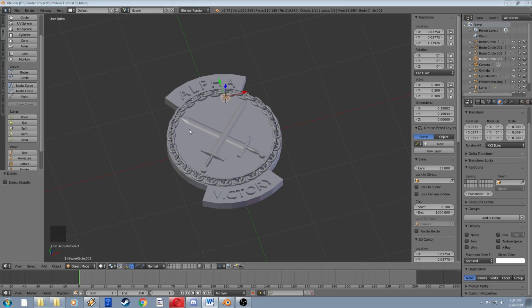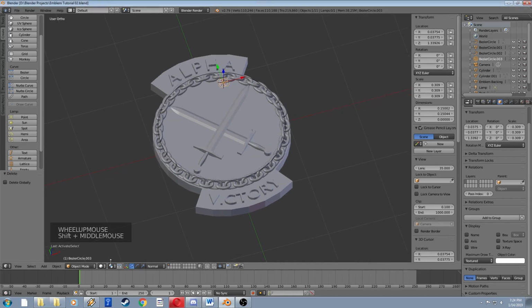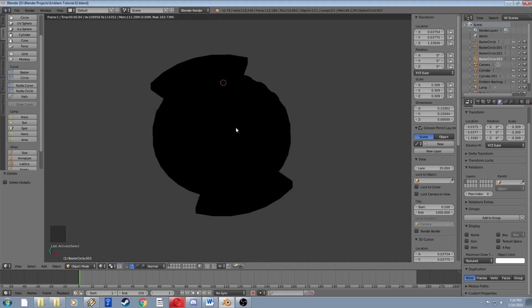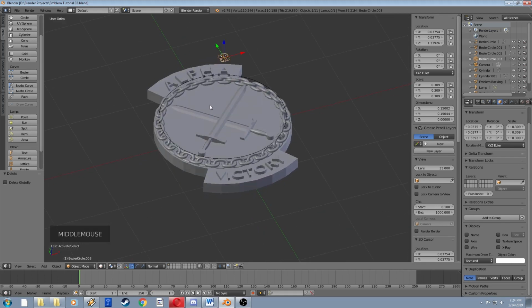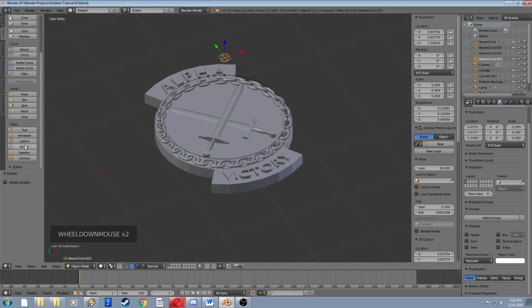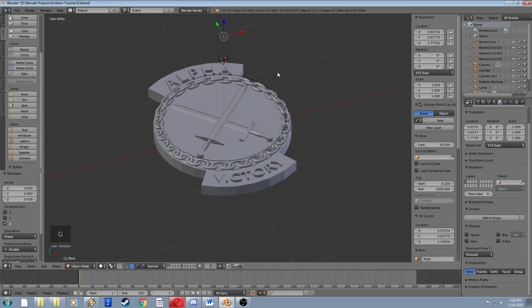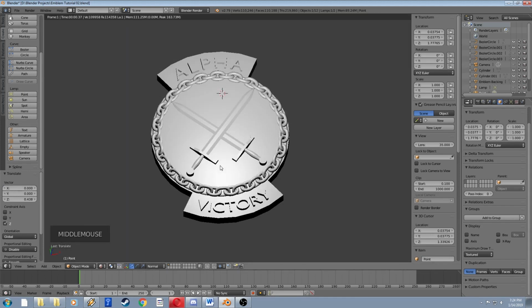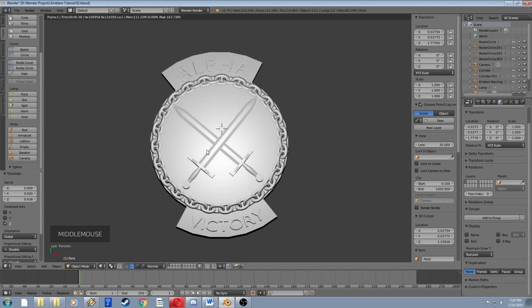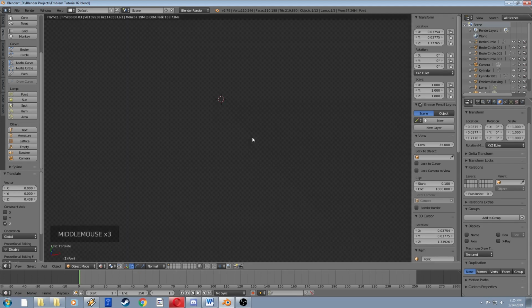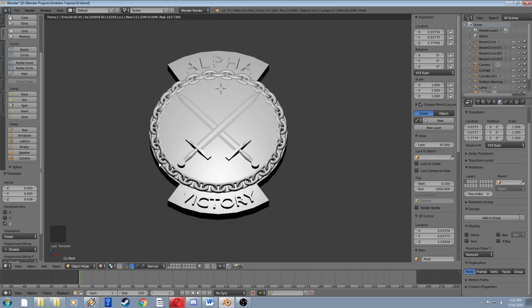The internal Blender render engine, if we want to see what it looks like, we can come down here and change our view from solid to rendered, and we get this thing that's pure black. It's pure black because we don't have any light sources in our scene. So actually, we can keep the cursor where it is, and we'll just create a point light source. All right, now we'll switch back to rendered mode. Now we've got this. Okay, this is 3D. There's some basic shadows going on here, and this is our 3D object.